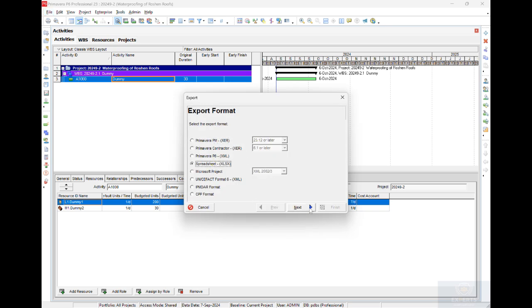Excel sheet. Next. Okay, here what do you have? I need to use activity relationship. You can do it, but I don't prefer it, because I like to make the scheduling by showing the Gantt chart and the activities together, so I can check the logic relationships and rearrange the relationships according to this. Expenses, no need for expenses now, and we explain in the course how to enter the expenses, so no need because we are preparing the baseline.